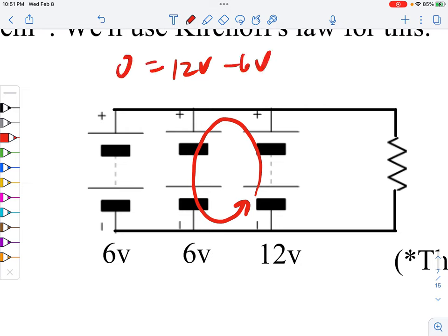What's going on here? Well, batteries have internal resistances. The 12 volt would have one too, but there would be some internal resistance inside this thing, and the other 6 volts would get dissipated. So you'd get some current that would flow into this little internal resistance. I'd have to take care of the other 6 volts, so you'd actually be pushing current back through this thing, which if it's a rechargeable battery would recharge it. That'd be a good thing, but if it's not, it just means it's going to heat the battery up a whole bunch and waste a bunch of energy.